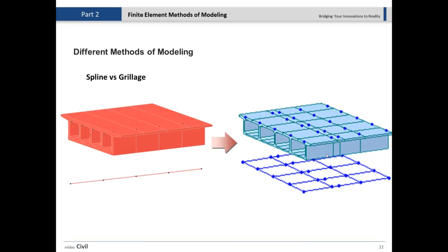Especially when we come to the curved geometry, for straight maybe we don't feel that much of a difference, because it's kind of symmetric. Every load goes vertically, so we don't feel it that much. But when it comes to curved geometry or irregular shapes, that is the time we see the effect of these transverse elements in guaranteeing the lateral stiffness more and more.